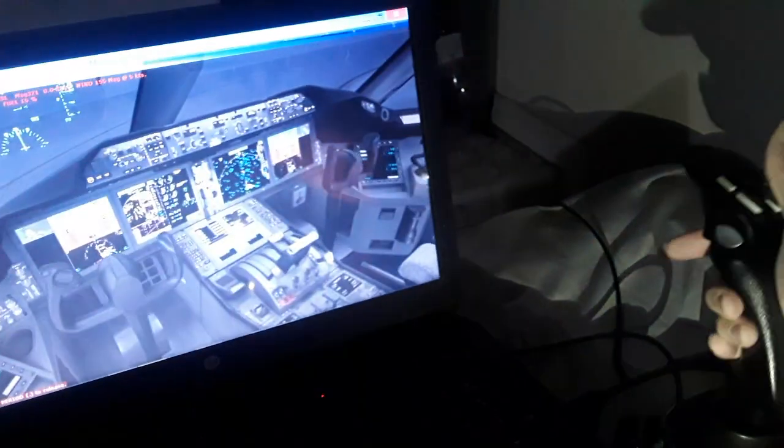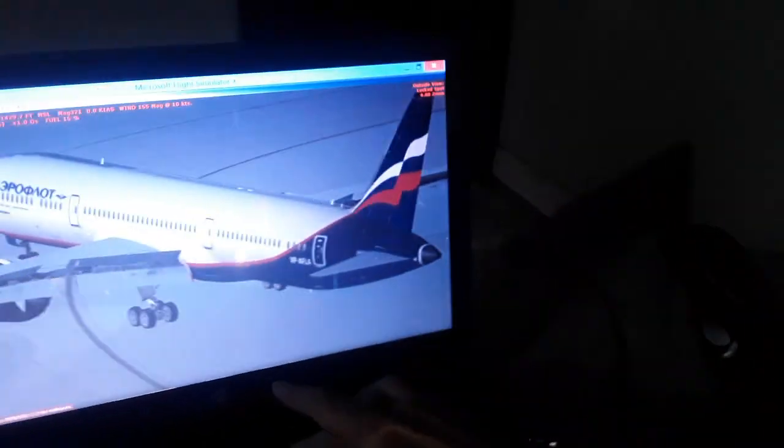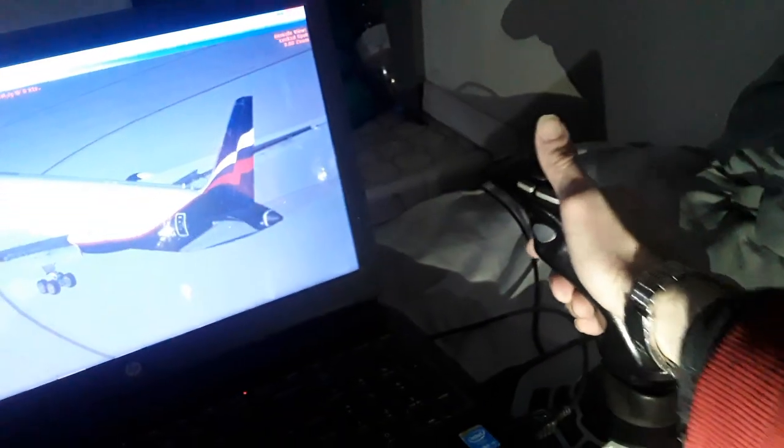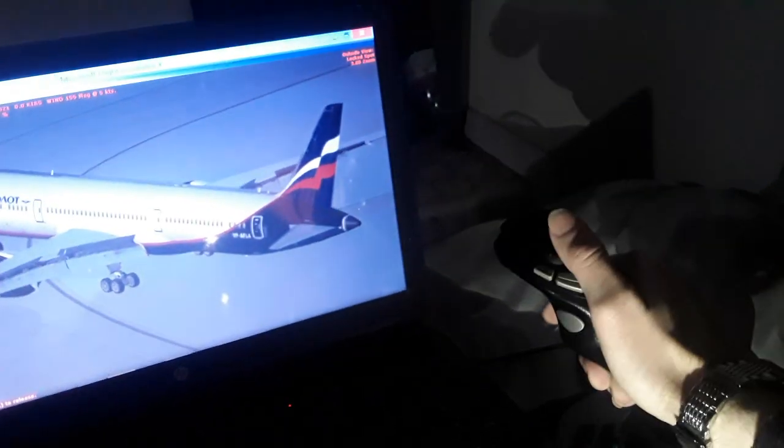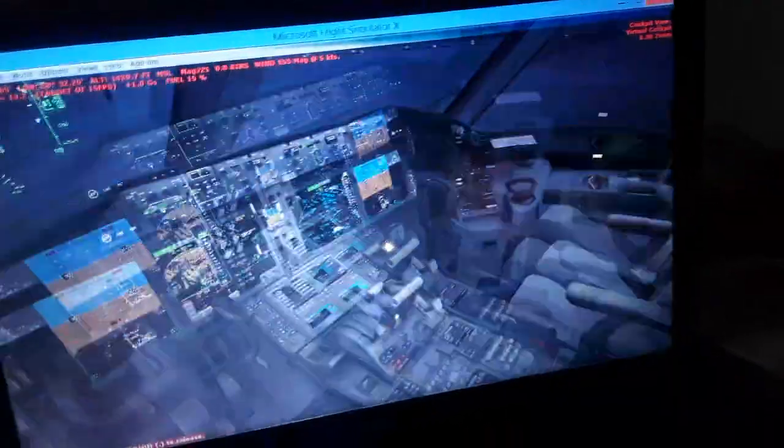The FADEC also controls the outflow valves, the 5th and 9th stage pressurized air from the engines, the bleed air, also from the bypass from the front fan. So we have bleed air for cabin pressurization, wing and engine anti-ice, air conditioning, ventilation, and also for hydraulic fluid tank pressurization. So you see when we move the flight controls they are controlled electrically, but the flight control surfaces are actuated hydraulically. So we need hydraulic pressure from the engines, which pressurize the pumps and the hydraulic fluids. You will see later in the overhead panel.